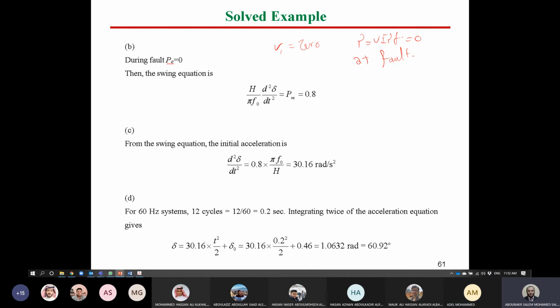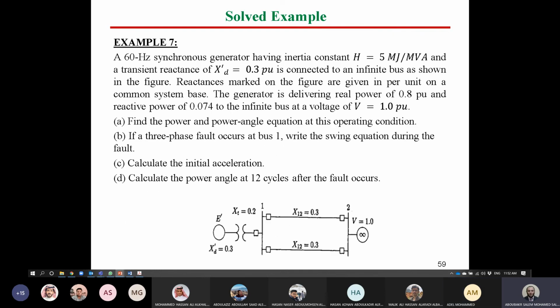But in terms of the circuit, let's have a look at the circuit here. This is our bus. What will be the power delivered to the load if you have a short circuit here? A short circuit here means all of the current is going to feed the short circuit, so there will not be any current or power moving to the load. Right? Yes.